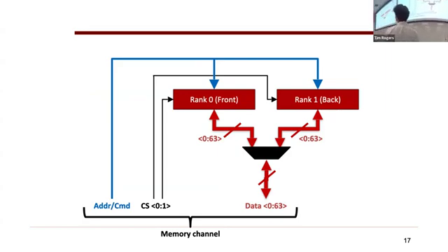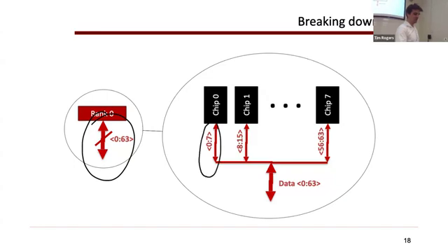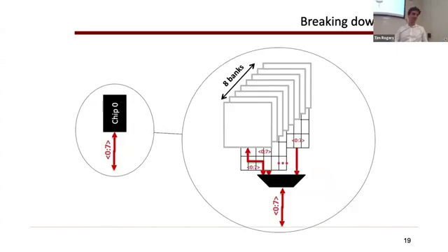So we've now got these boxes that basically say the same thing. I'm not going to say it again. You can break down the rank. Just to drive this home, because rank is probably the only thing you didn't know about before this class, is my guess. So the rank, the look of this is that I've got 64 bits blasting out every time. I get that by clubbing all these chips together, and each of the chips is giving me 8 bits to get concatenated into the wires that come out of this thing that's giving me 64 bits.